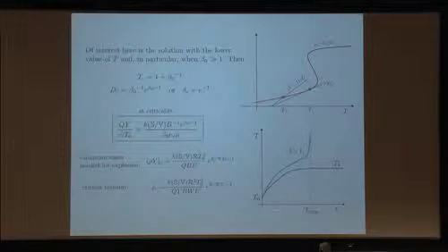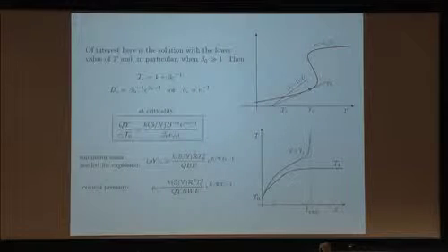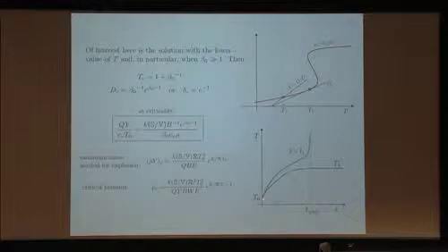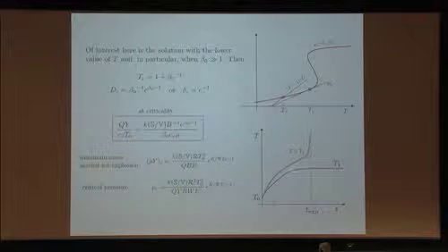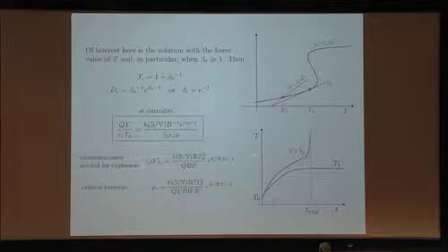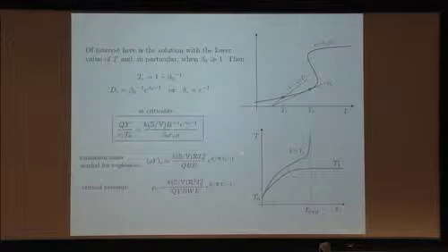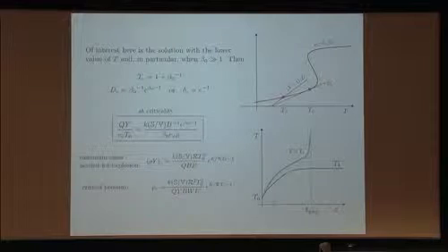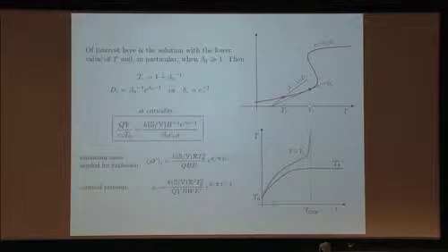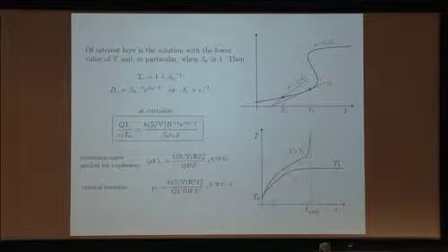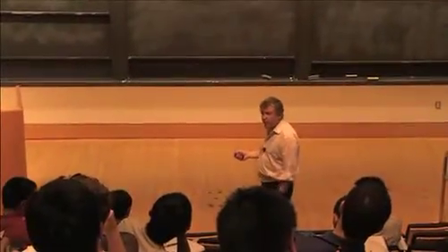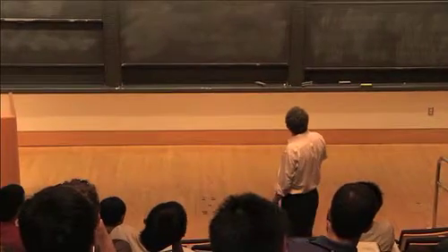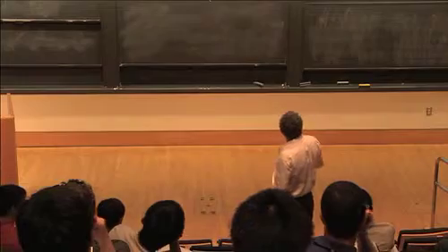So here is the time history for the two cases. You see for d1, which was below criticality, the temperature rises and eventually reaches the equilibrium state. But the green curve is above criticality; it's not the same green as in the previous slide. The other one was exactly at criticality. Here it's above criticality. Then clearly it will eventually explode, and there will be, as we call it, thermal runaway at a finite time, and that finite time is identified as the explosion time or the ignition time. Again, it's an asymptotic concept that can be identified very clearly, right?